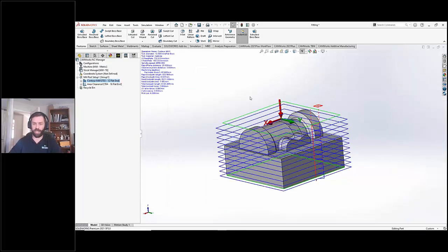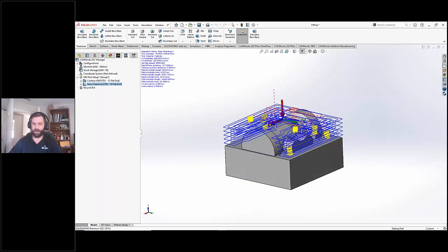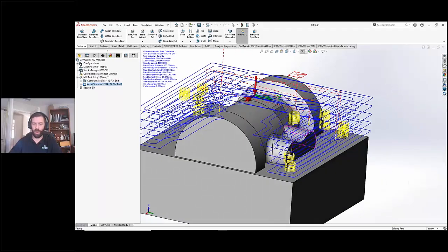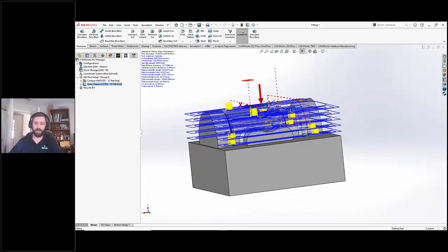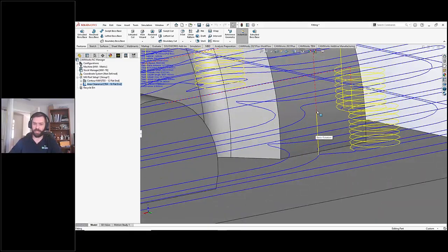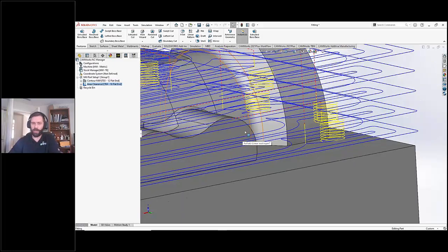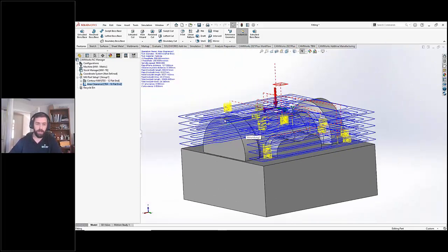Now, after making those changes, when I click through my toolpaths, like on area clearance, I can very clearly see where my plunge methods are. Makes it quite obvious to understand when it's doing a feed rate move or a feed move versus a cutting move. You have different feeds and speeds that control those different toolpath segments. So really understanding what the tool is going to be doing, what speeds and feeds it's moving at and when really brings a lot of clarity.